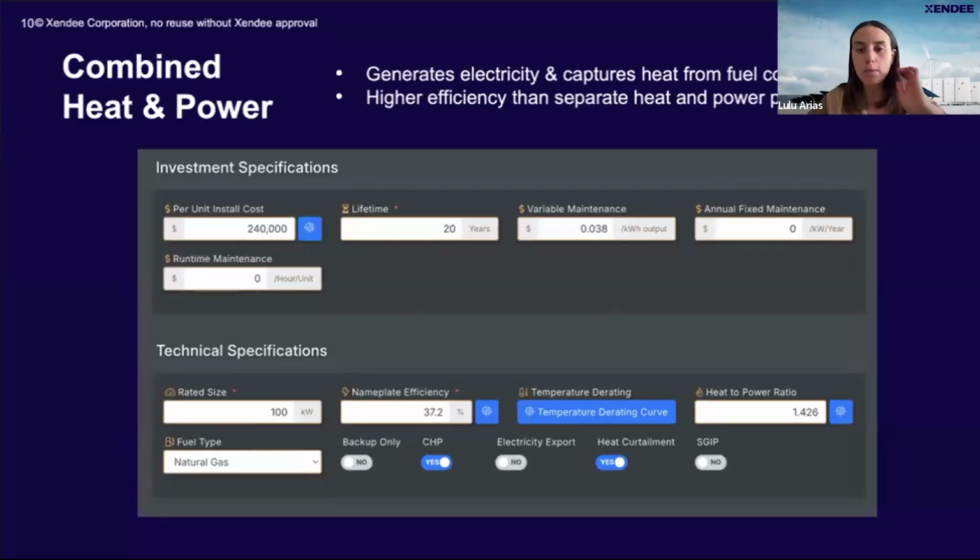And it's important to keep in mind that while we're focusing on the CHP specific settings here, generators like the CHP generators also have the standard non-CHP specific parameters that you're already familiar with. So this includes minimum and maximum load constraints, setting ramping rates to ensure that the model accurately reflects the physical limitations of your generator.